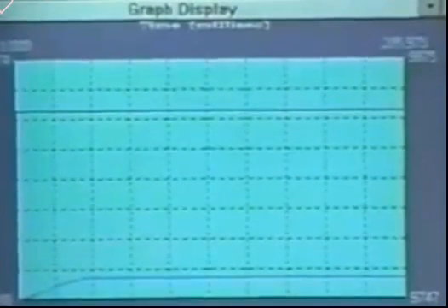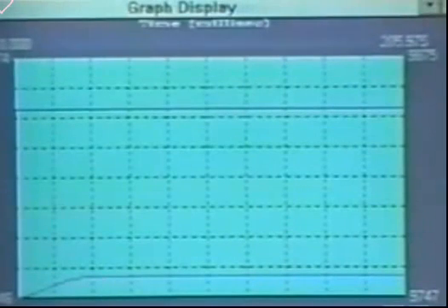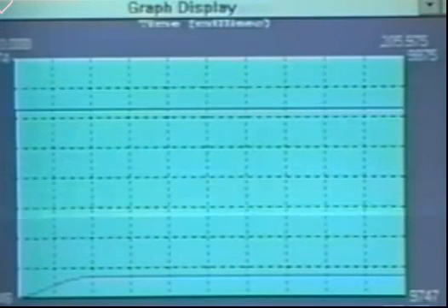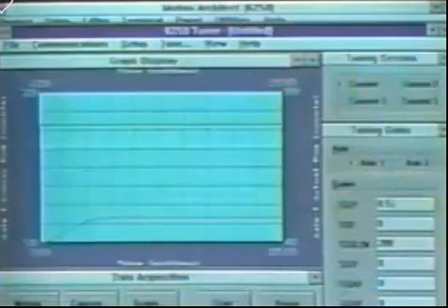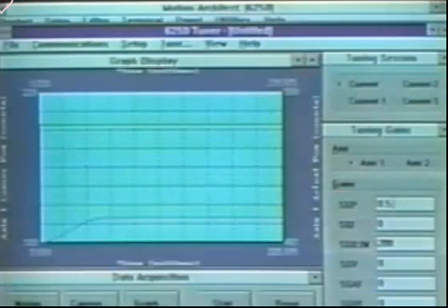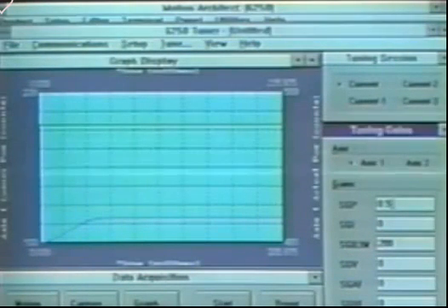The top line is the commanded position, while the bottom line is the actual position. Our goal is to have the two lines in sync. It does not reach the commanded position. We must increase the proportional gain until it does. We will first increase it to 5 and then start tuning again.